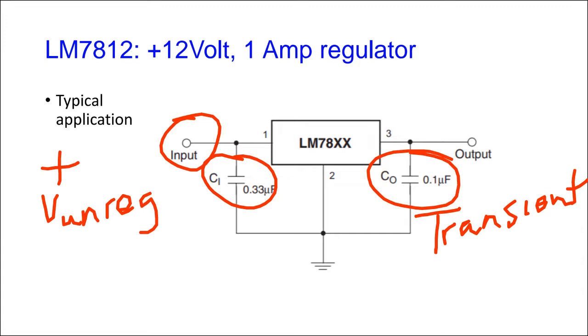Right? There are always little, because once you have a circuit board and you're in the air, for instance, wherever you're sitting down now, you have 60 hertz electromagnetic radiation present because of the 60 hertz power supply in the wall outlet close to you. Okay, you also have a lot of noise on the power line, because of the type of power supply that your laptop, for instance, may be using.